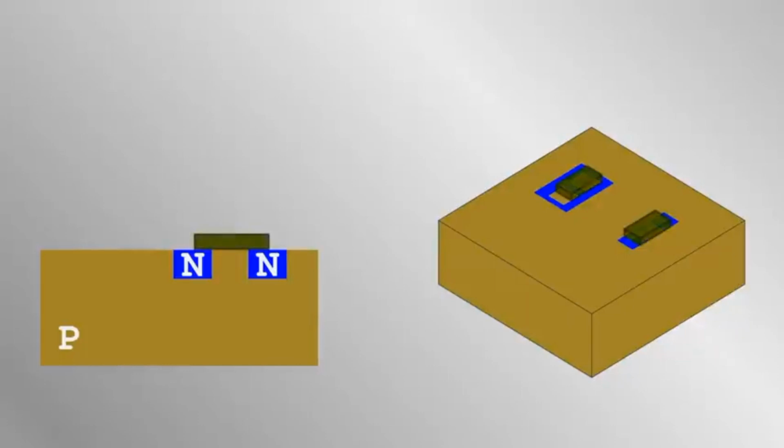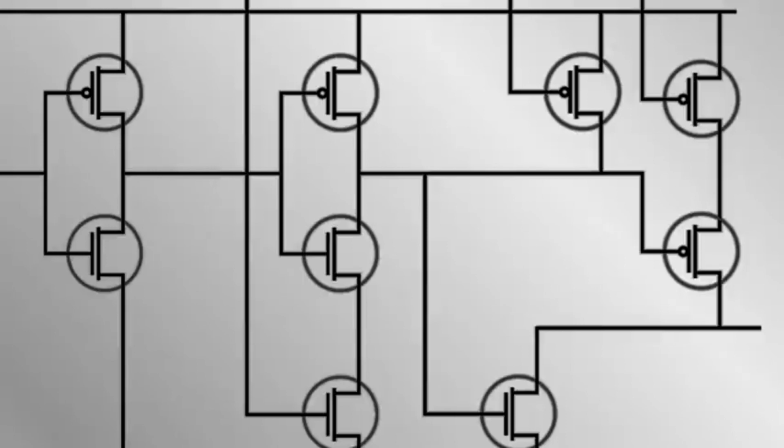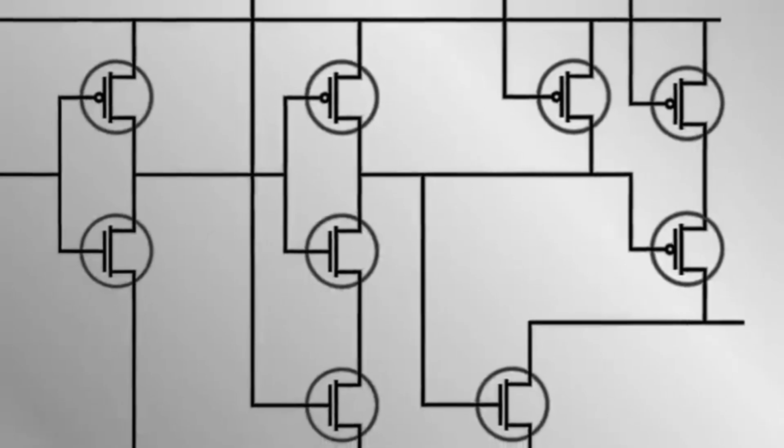Next, the silicon oxide is deposited and etched, and finally metal is deposited and etched away to leave metal channels on top of the die. These metal features form not just the conducting terminals of the transistors, but also the tracks equivalent to wires in a circuit, which connect the transistors as required. Every time, photoresist is deposited, exposed through a mask, gaps are made and the die is etched. Finally, the billions of transistors are assembled and connected together by this method.